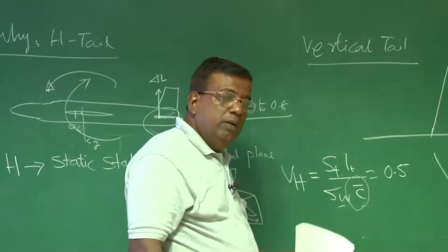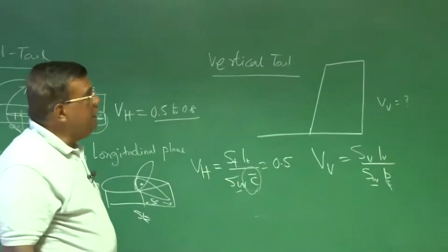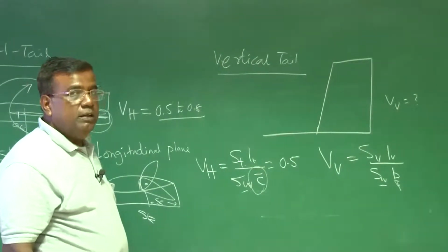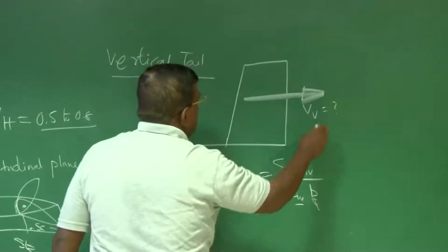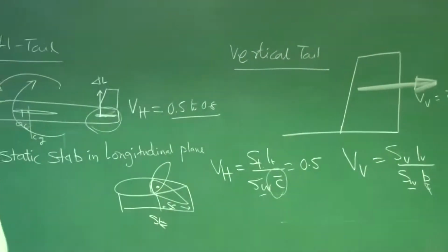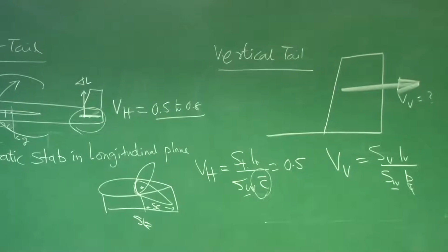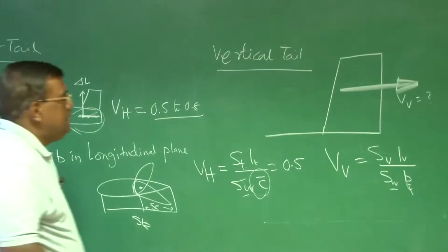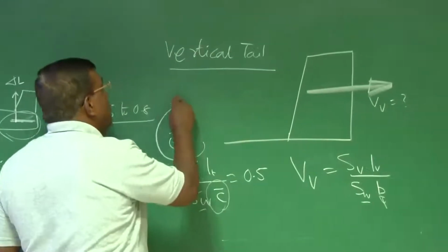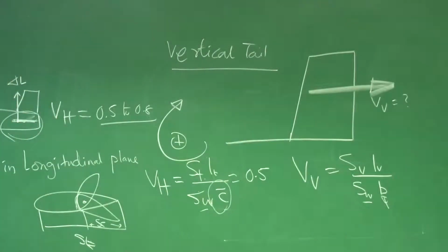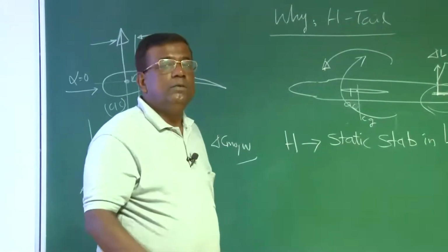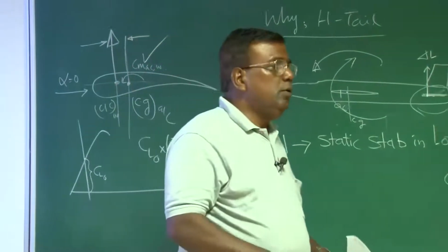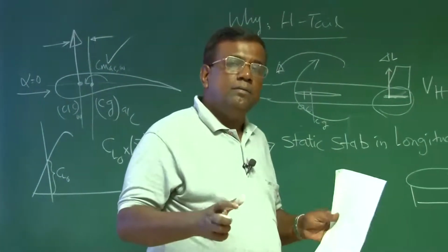But at the same time, what we miss generally, please understand, if I am increasing the vertical size because we are afraid, then actually I am encouraging drag due to vertical tail or vertical fin. I am encouraging it to become more and more, and the CG will be somewhere here. This will give a nose-up moment. So if you have a vertical fin and unnecessarily you have put a larger size, as you try to accelerate, you may have pitch-up tendencies. So that also needs to be careful when you are going to do the finer design, finer evaluation.